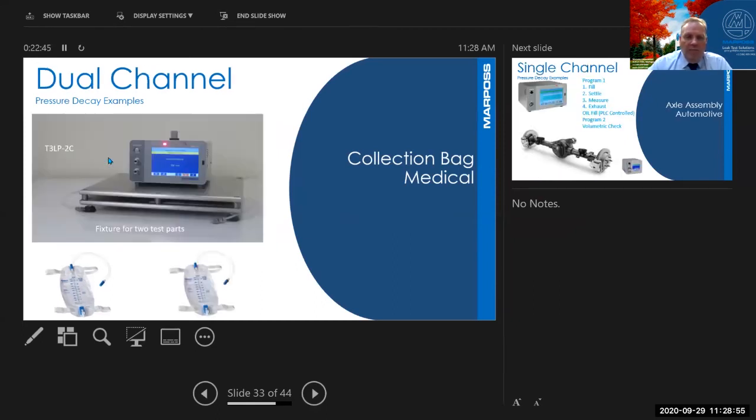But we can also do the same thing with a dual channel configuration. One of the things you'll note is we've got 2 leak master ports on the front, but now we can load 2 parts, hit a single start button, and both parts are tested at the same time. And this is what we refer to as a dual channel.